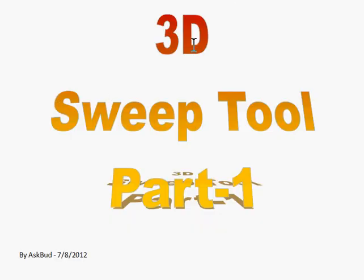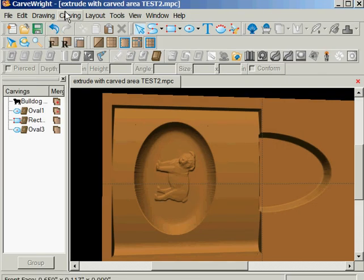So again, we use the sweep tool to shape our oval in order to be able to put that oval as an inset within the dome or the extruded area. Made the oval a negative merge, and in this case we had to invert the image in order to accomplish what Clint needed.